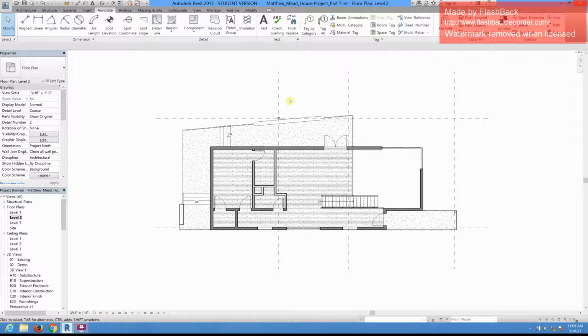You can create a template. All right, so you duplicate that floor plan that has all of the things on there that you don't necessarily want to show. Well, you can create a template for a standard elevation template. Okay, so you can go through and uncheck all the things that you don't want to see, and create the template.